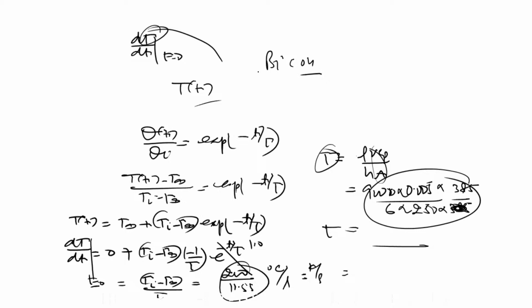A fin question. In that question, I'm going to send you the question. Please listen. In this question, they have given the Biot number based on the radius of the fin as the characteristic length, which is 0.04. So the criterion is not 0.1, the criterion is 0.04. And here it is clearly mentioned you have to use the Biot number based on the radius of the fin as the characteristic length.